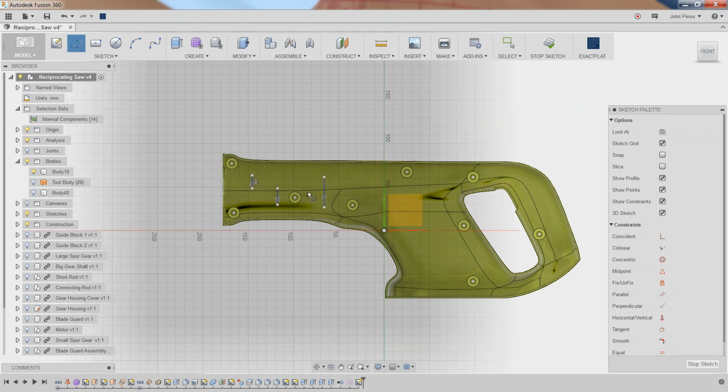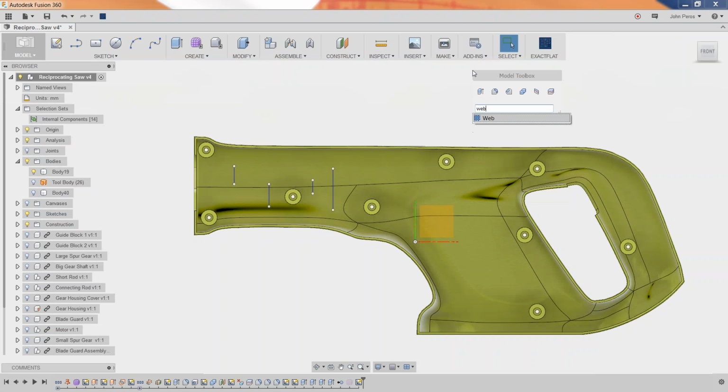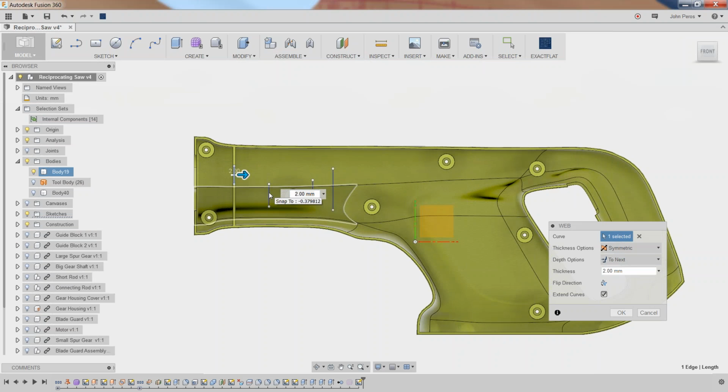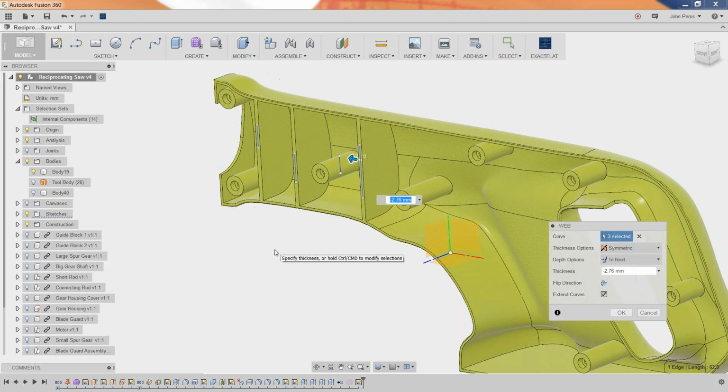And I'm putting these lines out, and none of them are the same size or anything like that, but it doesn't matter when I'm doing a rib in Fusion, because when I use the command to create these ribs, Fusion is automatically going to find the boundaries for me, and it's going to take those ribs up to the boundary of that solid body that I'm working with.